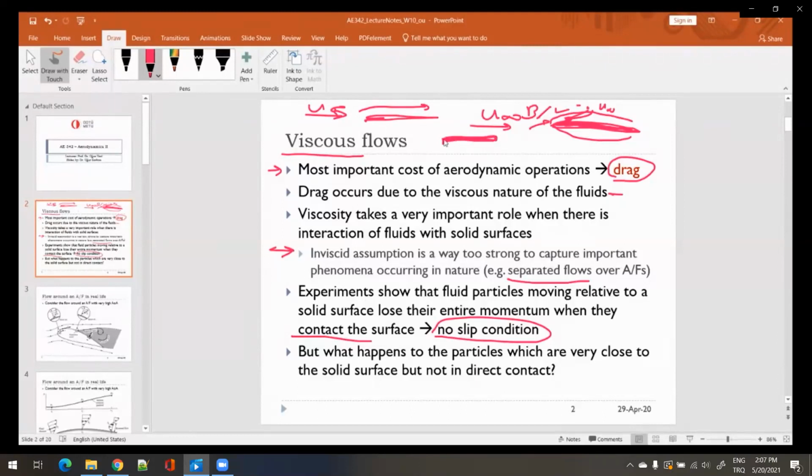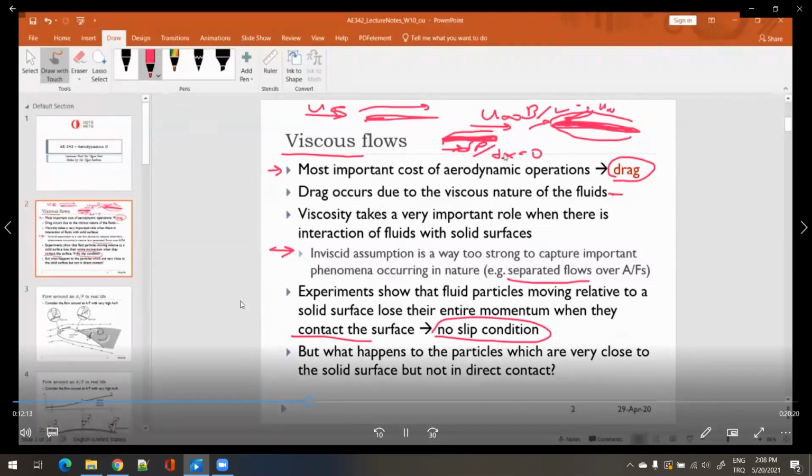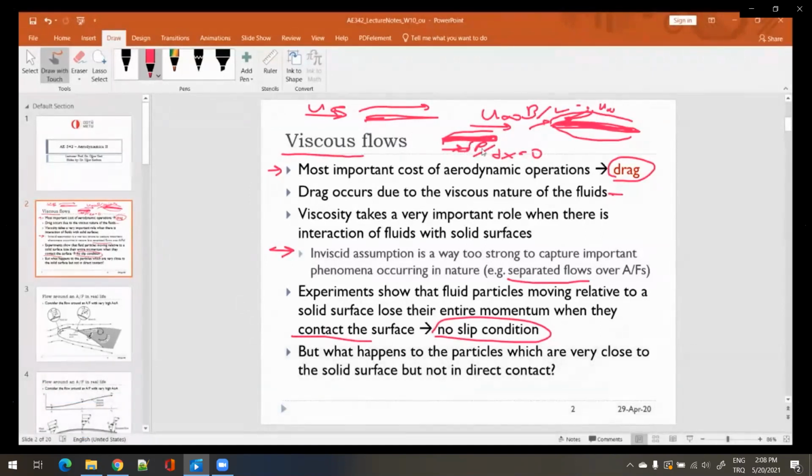This flat plate is such that the pressure gradient along the plate, dp/dx, is zero. There will be a boundary layer around it, but the flow outside will have constant U infinity. We will first try to understand this problem in terms of its flow physics and mathematics. Then we will ask, what if this pressure gradient was not zero, or what if we have some varying U infinity? How should we modify our equations? We will see those later.